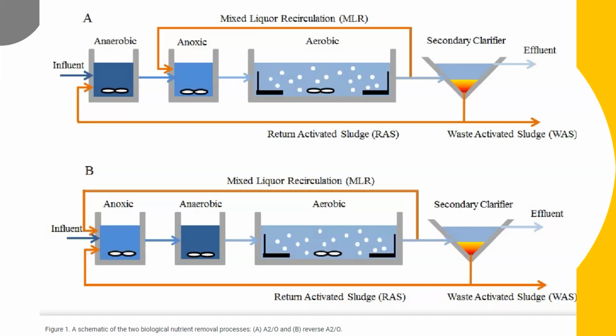and protecting that anaerobic zone from nitrates is very important. Additionally, it needs to be protected from high amounts of dissolved oxygen, which may be coming in your return activated sludge, or at some facilities, if you have aerated grit removal, for example, you may be hindering your anaerobic zone creation by adding air early on in your headworks processes. So ensuring that the return activated sludge is low in nitrates and dissolved oxygen, and that your pre-processing of your influent also doesn't add too much oxygen will help in your phosphorus removal.